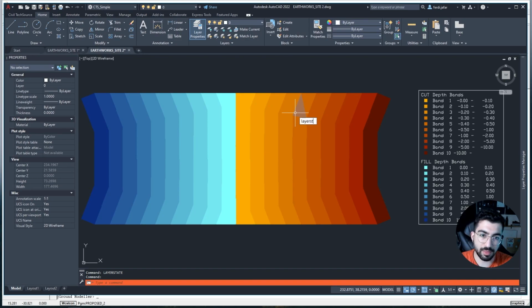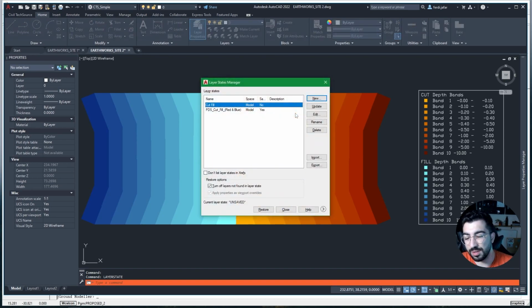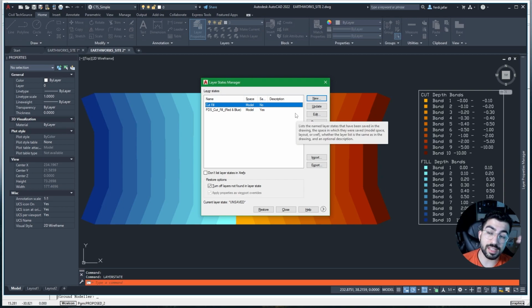So I think there is two types of cut fill. You can show the fill in blue. The cut is always usually in red, and that I think is taken from the embankments, like the gradient slopes. When it's in cut, it's shown as red. When it's in fill, it shows in green. But you can also show blue as in fill. But I usually go for the red and green because I reserve the blue transitioning for my float compensation drawings.